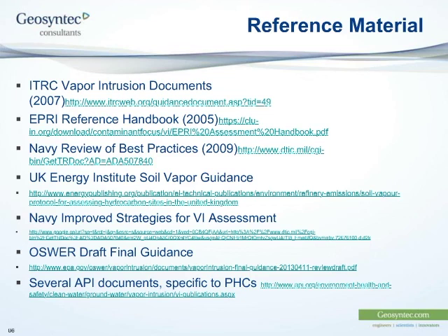One thing that's interesting, I didn't mention this earlier, is that pressure transducers can measure a difference as low as 1 Pascal. Barometric pressure, which is 101,000 pascals, can vary by up to 3% per day, which is 3,000 pascals. So the magnitude of the change in the signal compared to the sensitivity of the instrument is huge.